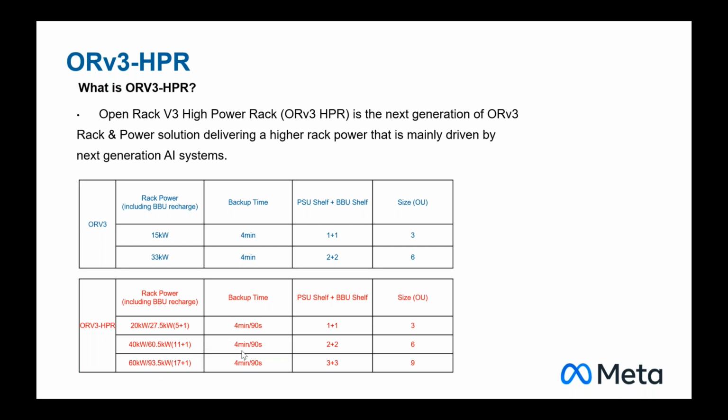For the BBU backup time, we have 2 flavors. Same design. If people want longer backup time, 4 minutes, you get 4 kilowatts per BBU module. But the same design can support 5.5 kilowatts for 90 seconds. Okay. Next page.